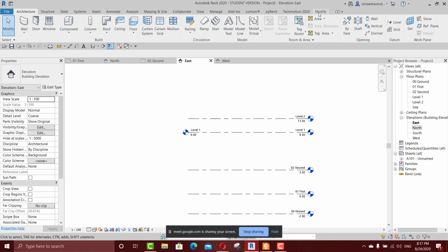Your friend is asking me if we do have a shortcut for the offset. Of course we do have the OF. I just click now OF. You can see now this small icon which represents the offset. I could even put it as a number or a graphical one.